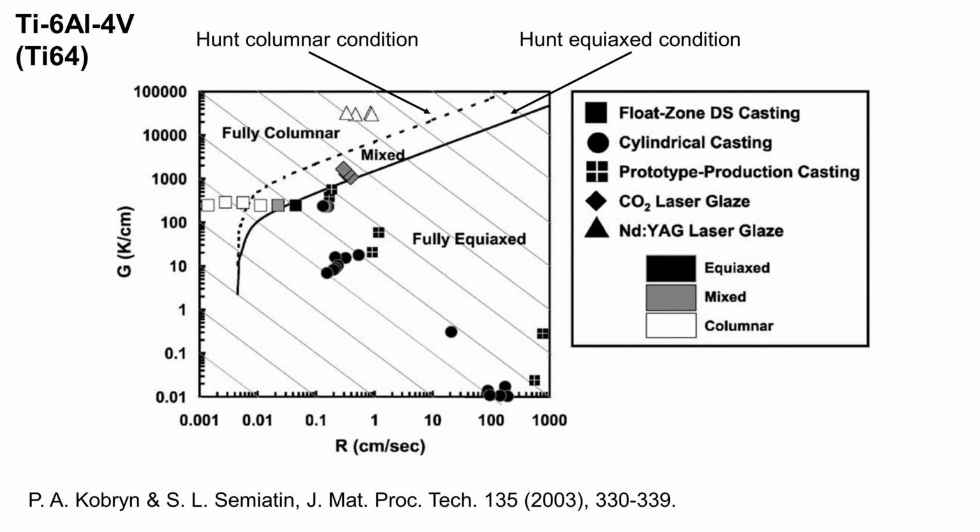Our research team decided to look into this grain refinement method in more detail, specifically investigating the realms of possibility with high-deposition-rate directed energy deposition AM processes like wire arc AM or WAM, which are of high interest to aerospace industries. The first step was to use the models and previous research available to establish the theoretical bounds of what was possible with Ti-6-4 through solidification manipulation. This was done by Dr. Daniel Dreelan. I'll skip the model details. You can find more information in our published paper, which is in the video description.